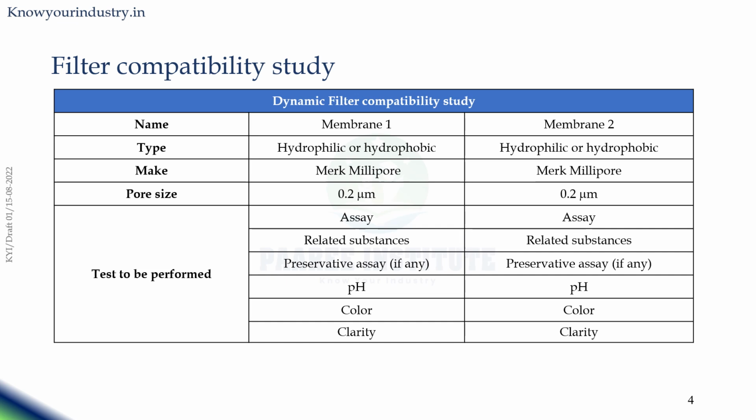The samples shall be tested for your critical quality attributes to see if there is any difference in your test results in comparison with your control. If there is, then you may have to relook at your filter membranes, followed by the filter validation, where you show that your product can be aseptically filtered. It is applicable for injectable as well as ophthalmic solutions.